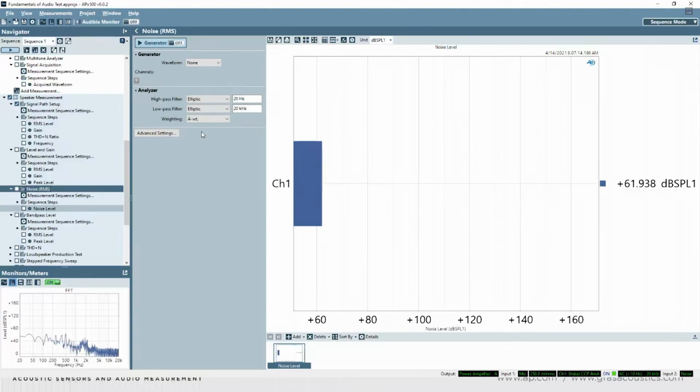That is a very complicated question, actually. So it depends, and I think we'll best take it offline. I will say this: if you stimulate a device that is perfectly linear and time invariant, a cable, for example, with white noise, the FFT of that will be a straight line. But it depends on your test signal, if you know how you deviate from that and what the behavior of the device is.